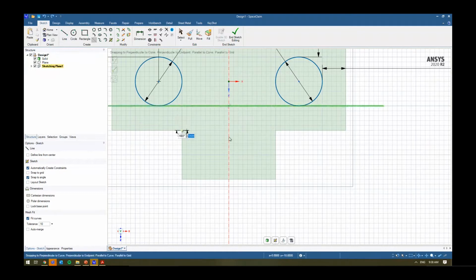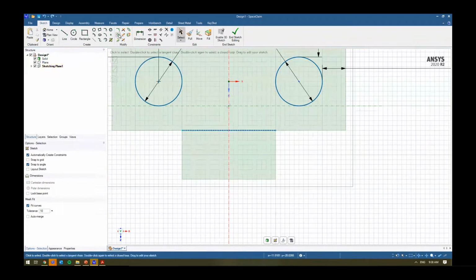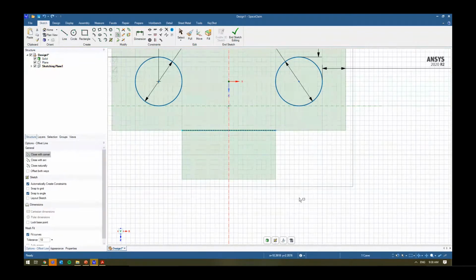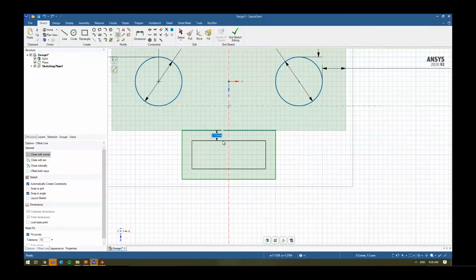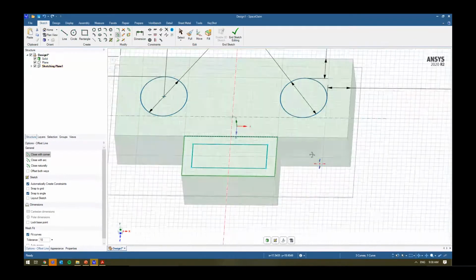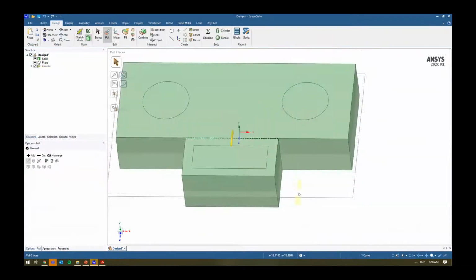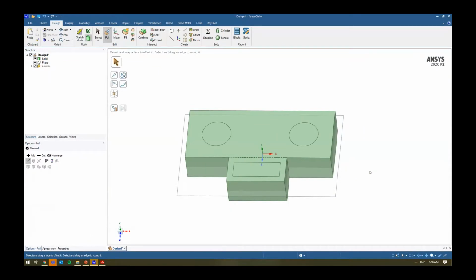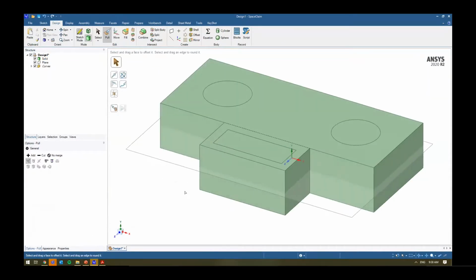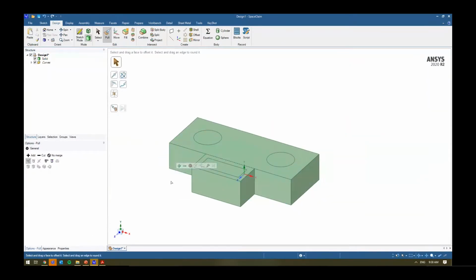I've got this construction line that I can create, right? That way, when I select all of these lines, right? So let's select them. 1, 2, 3, 4. I can easily drag that in. Let's drag it in, say 5 millimeters. No, that's way too much. Let's just drag it in 2 millimeters and it's good to go, right? D on my keyboard takes me into 3D mode. There are some shortcuts, so H brings me into home as well, right? Go in and select that.